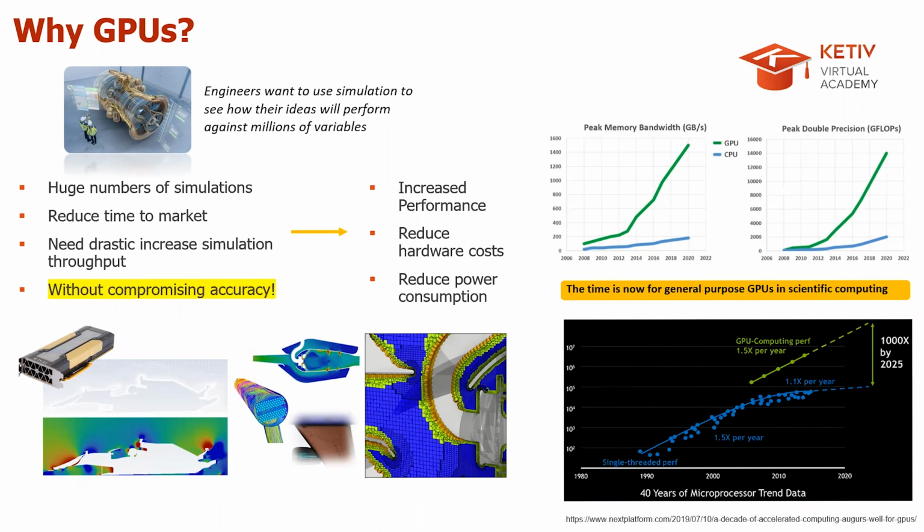Sometimes we'll look at reducing our cell count, we'll look at simplifying the physics that we're adding to our simulation, or we'll go ahead and start investing in hardware resources so that we can get good performance gains, get high simulation throughput. Now, traditionally, conventionally, we've been using CPU cores for the parallelization, but as we can see over the past couple of years, there's been a lot of buzz around GPUs and what they can do in comparison to CPUs for getting this high simulation throughput.